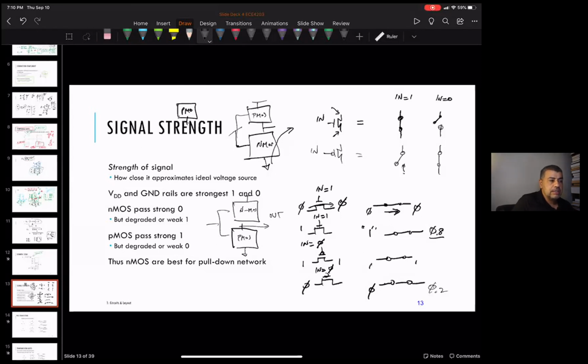And then the next logic gate that you're driving, you're driving it with a weaker signal, and you'd sort of propagate that weakness through your system. So anyway, we're adding this concept that not only N MOSFETs and P MOSFETs are switches, but they're switches that have a preference as to what kind of signal they're passing. Do you guys have a question about that?